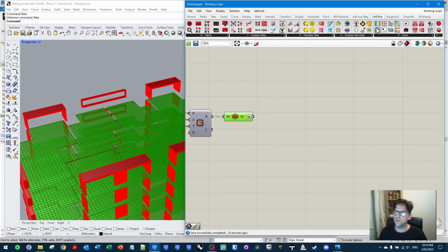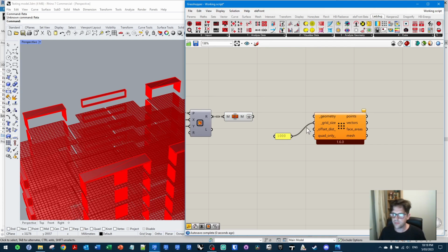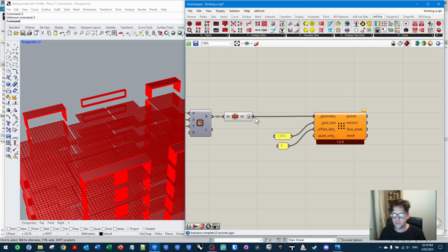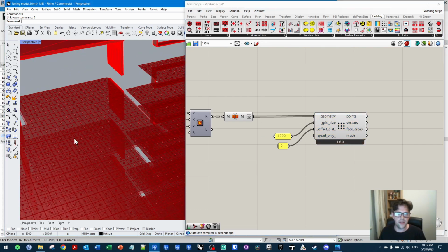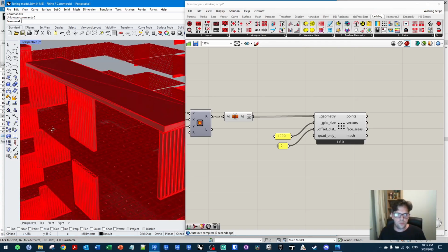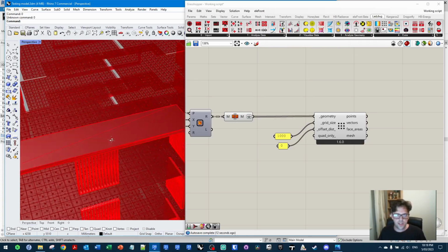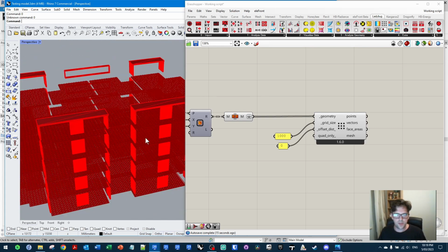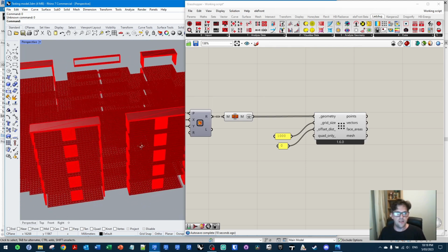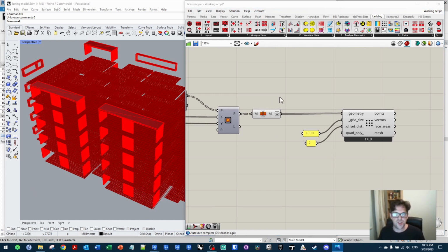Now, if I go and resample these, you're going to notice that this is going to be a very even sample. So if I use the same settings as before, they're going to be very clean. Look at that, 1 per tile. Very clean, evenly distributed, almost 0 error or bias from what I can see. Perfect. So that's a really great technique that I've used quite often, even in my own work, to really just resample surfaces into something very much workable compared to what we get with the default Ladybug mesh attempt.